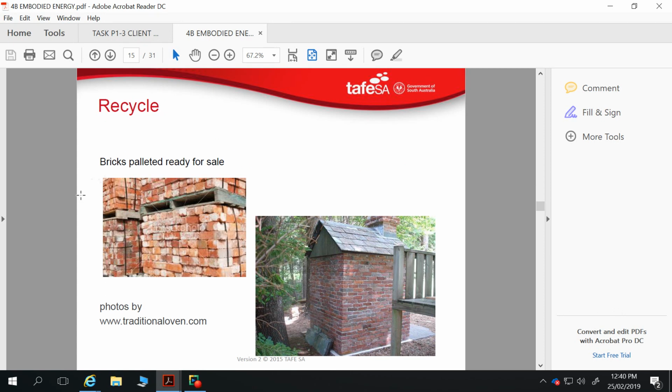Old red bricks, fantastic for reuse for paving. And has everybody seen building projects using old bricks? Actually, possibly, yeah. My sister had two buildings, a garage and a laundry. They've knocked down the garage and they've used some of the bricks as just parking, because they can't be used for anything structural, because the strength of them is not as strong as it was. Yeah, so in some situations they can't be reused.